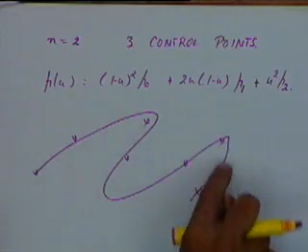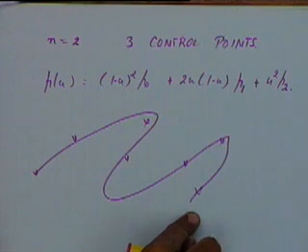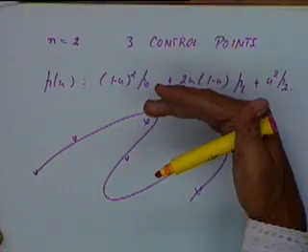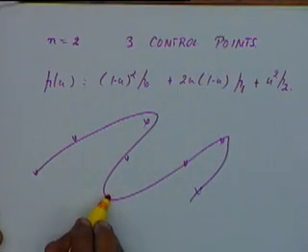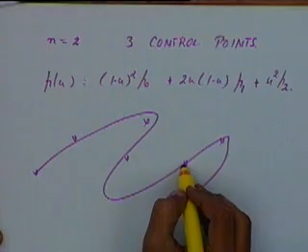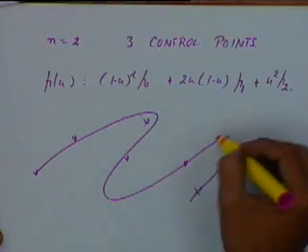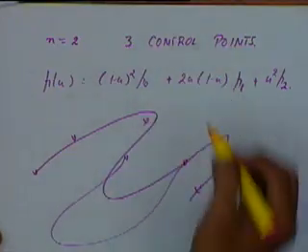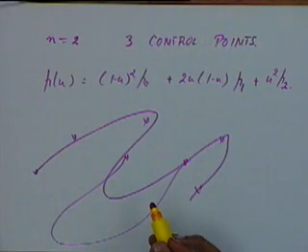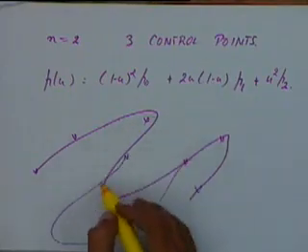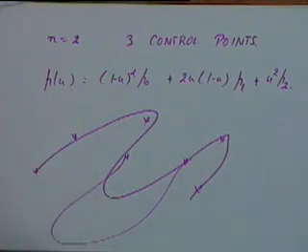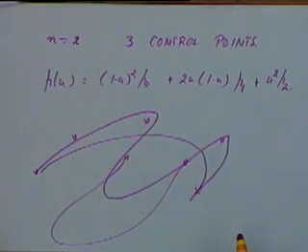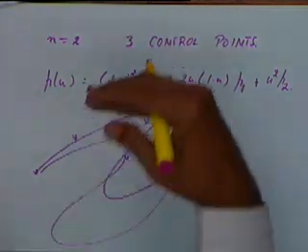The outer limits of this curve are bounded. It can't go beyond a certain limit. It will always remain within a closed polygon. For example, let's say these points are positioned wrongly, the curve can go like this, because the curve has to pass through all those points. That doesn't happen in the case of Bezier curves. If I draw the Bezier curve for the same points, it has to remain within a certain area. The curve will probably look something like this, or it might go within it, but it will remain within a closed polygon.